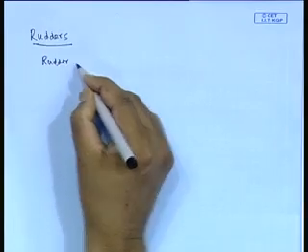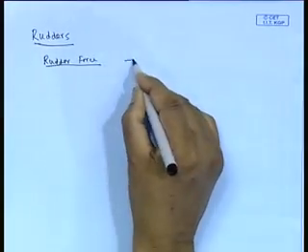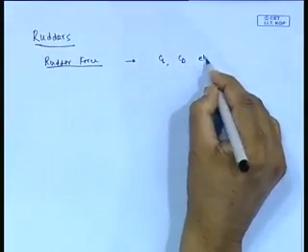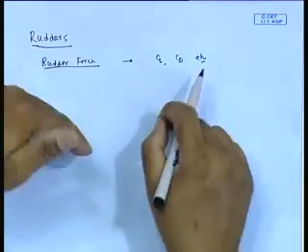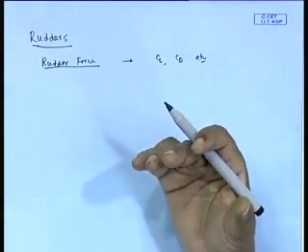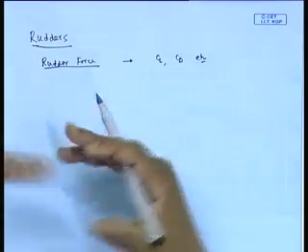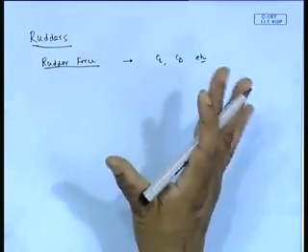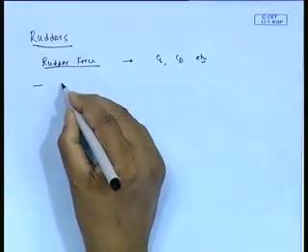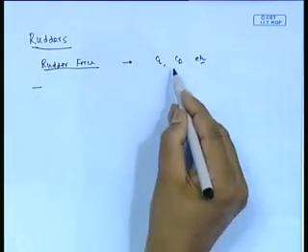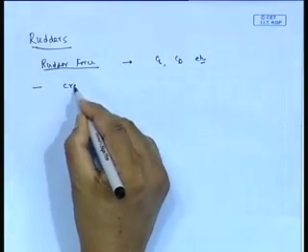Initially, I am going to say even simpler than what we have done in CL, CD. Rudder force we defined last class in terms of basically CL, CD, etc. We resolved it, but not going even to that. There are some even simpler semi-empirical formulas which would be very useful to make a quick estimate for rudder forces, etc. Now, basically this force will depend, as we know, on CL, rudder force or CL, CD is the same thing, depends on cross